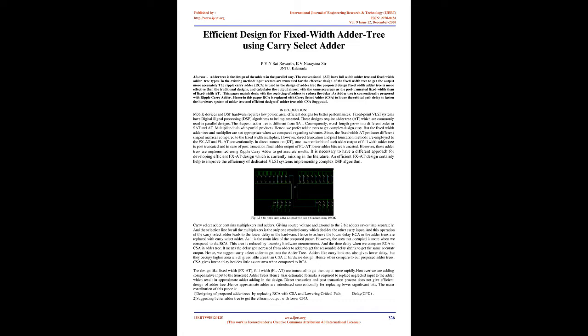This paper mainly deals with replacing adders to reduce the delay, as the adder tree is conventionally proposed with ripple carry adder. Hence in this paper RCA is replaced with carry select adder, CSA, to lower the critical path delay and speed up the hardware system of the adder tree, and an efficient design of adder tree with CSA is suggested.